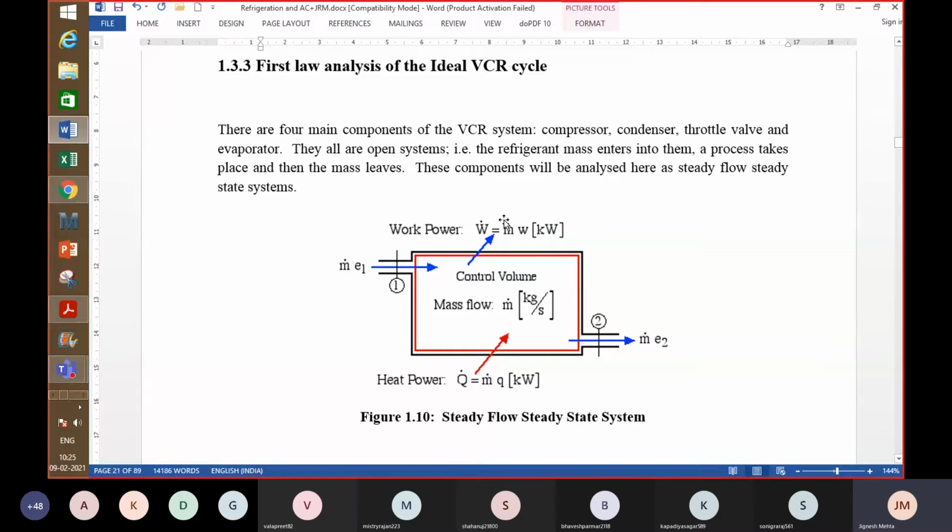Primarily, what is the rate at which you want to produce cooling, right? That is one of the important things that one would like to know. Or you are given a task to build a system which provides a particular cooling rate. For example, when you purchase an AC, you are asked what capacity you want, whether you want 1 ton of refrigeration or 1.5 or 2, right? Similarly, you can have other applications, even much larger systems, or some very small miniature systems also. So cooling rate is one of the important parameters.